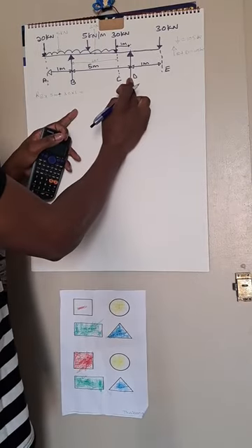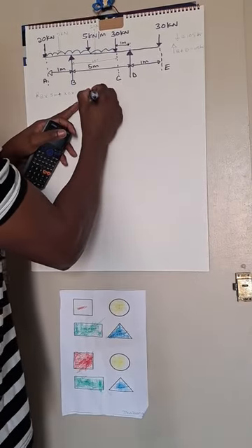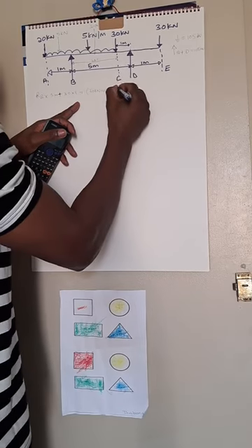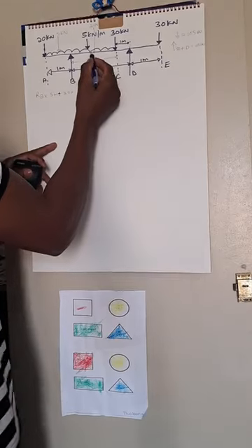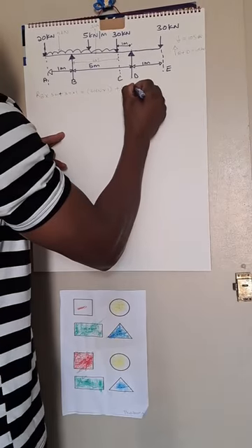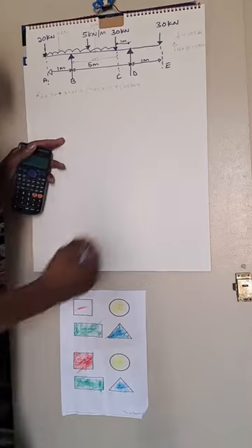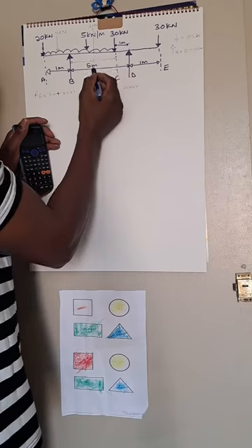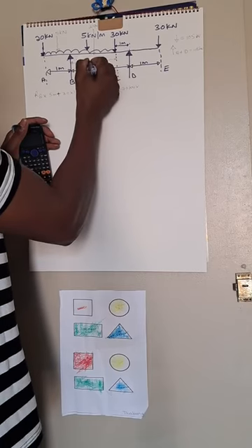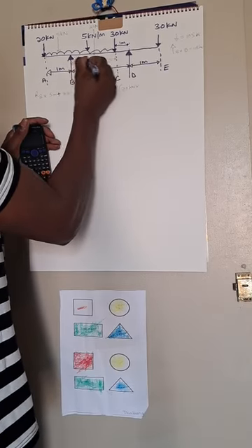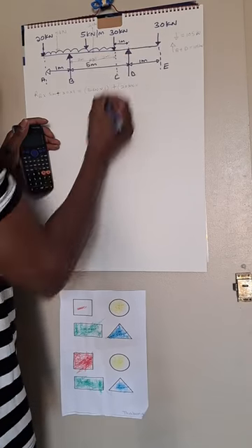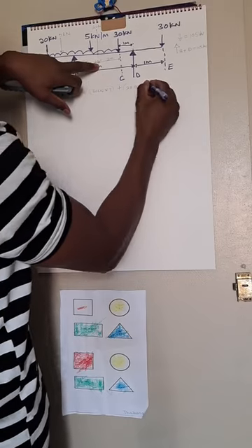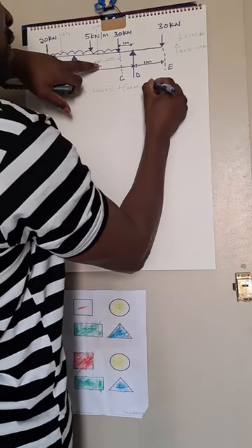All the forces that are going to the same point B, so we have 30 kilonewtons times the distance to point D, which is 1 meter, plus 20 kilonewtons times... Now if you check here, the 20 kilonewtons is cutting 4 meters into half, which is to say from this point to this point becomes 2 meters. From this point to this point it becomes 2 meters. So we already have 2 meters for 20, so 2 meters plus 1, we've got 3. So it's 20 times 3 meters.